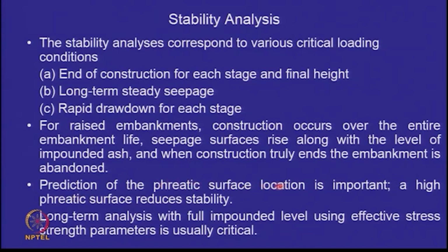Prediction of the phreatic surface location is important. A high phreatic surface reduces stability. Long-term analysis with full impoundment level using effective stress parameters is critical.